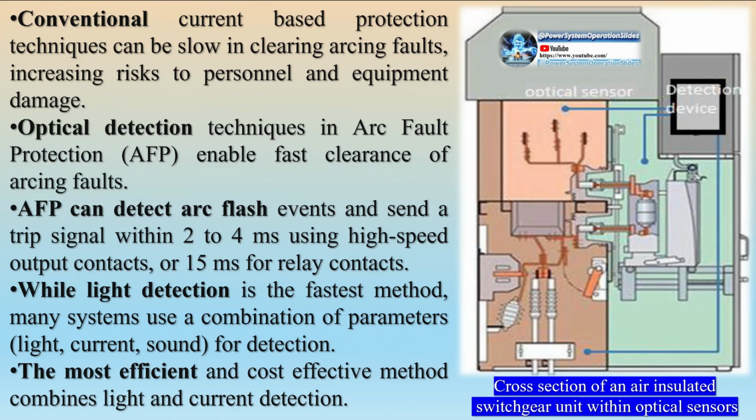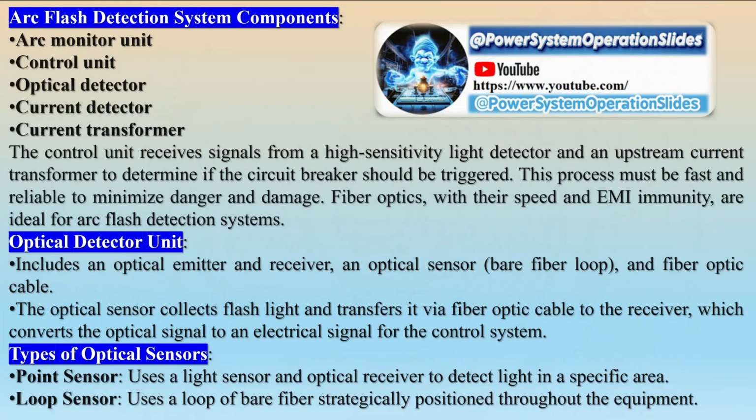Bus differential protection: based on Kirchhoff's first law, the sum of currents entering and leaving a bus must be zero. It protects a bus with multiple feeders by ensuring the sum of incoming currents equals the sum of outgoing currents. Fault detection: an internal, in-zone fault is indicated if the current sum is not zero. External faults can cause high currents that may saturate CTs, current transformers, leading to false differential currents. Challenges: CT saturation can cause incorrect relay operation by providing false current magnitudes. Manufacturers use algorithms to maintain relay stability and prevent unnecessary operations during CT saturation.